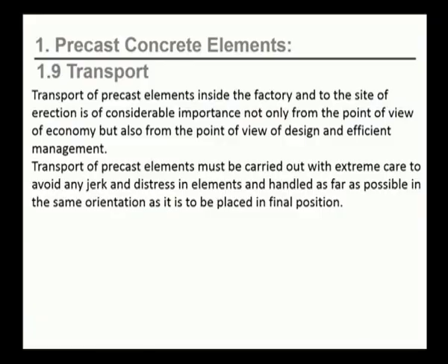Transport of precast elements from the factory to the site is of considerable importance, not only from the point of view of economy, but also from the point of view of design and efficient management. The transport of precast elements must be carried out with extreme care to avoid any jerk and distress in elements, and handled as far as possible in the same orientation as it is to be placed in the final position.